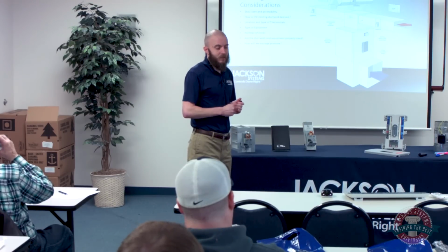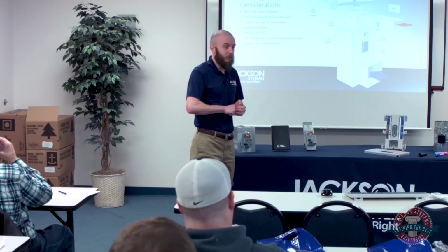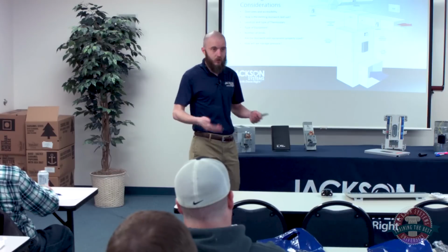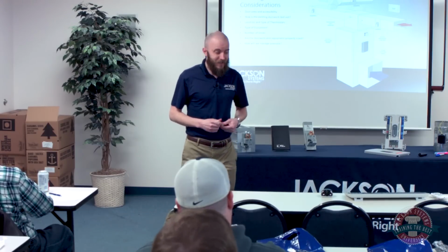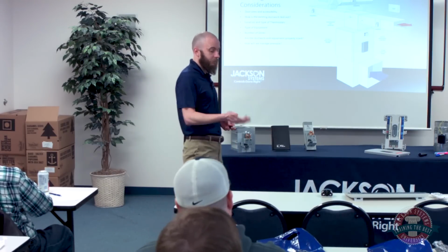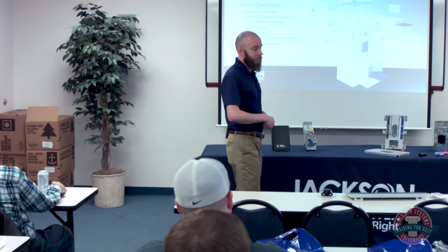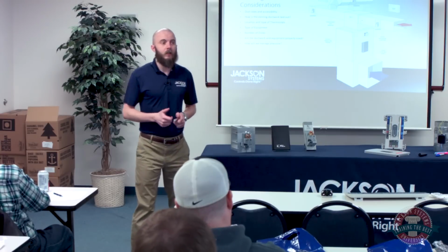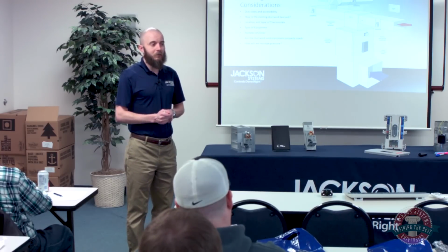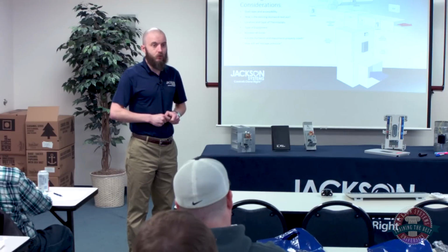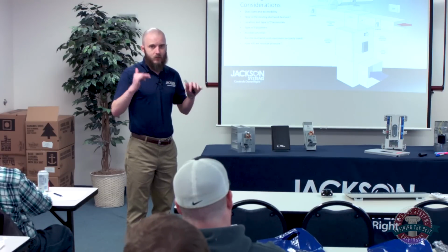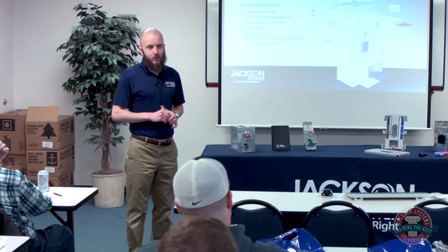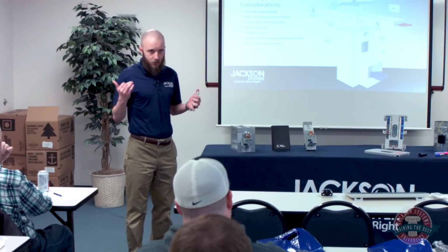So in a lot of cases, some variable speed blowers will be fine on their own without any additional pressure controls. If you put in some further pressure control, you have to be very careful sometimes. If you put in a bypass or something like that and you have a variable speed blower, you want to be very careful because then you have basically two different systems that are going to be responding to pressure potentially differently. You don't want to end up with a situation where you're going to have those systems fighting each other.